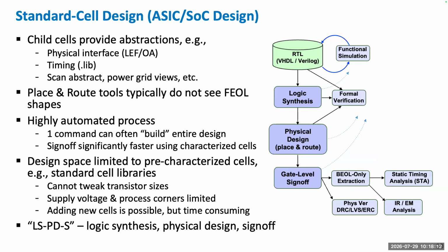And fortunately we can. I mean, this is pretty standard too. I'll call this either standard cell design, ASIC or SoC design throughout the talk. This is really the workhorse of digital design today. And I think the key thing that it leverages is abstraction. So the instances and the objects you're using in standard cell design or ASIC design, they have abstractions which give you the enough information that you need, but abstracts out all the details that you don't until you need them later. So that's the key thing.